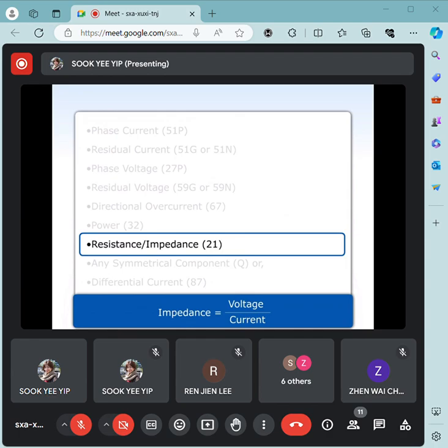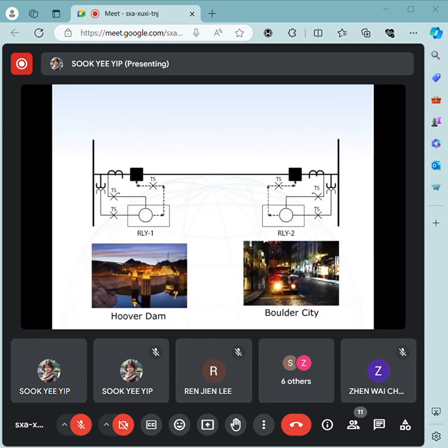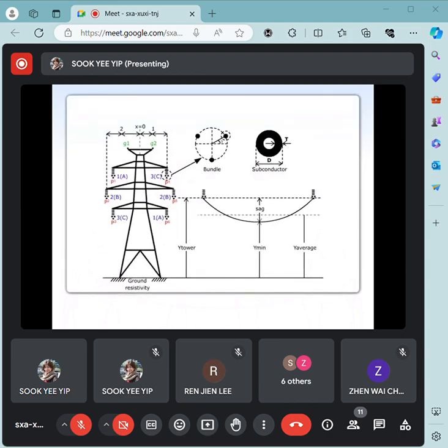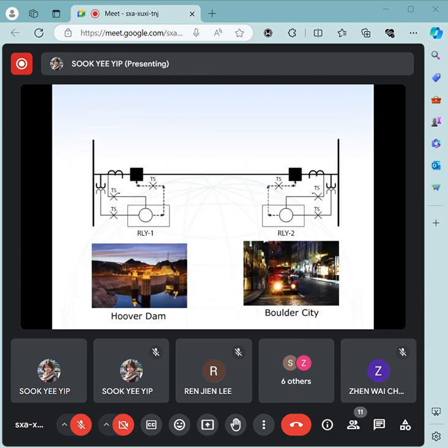In order for this solution to work, you need to know the impedance of the transmission line. You could measure it with fancy equipment, but it's usually easier to calculate it using the size of the wire, length of the transmission line, and spacing between wires. Let's imagine that we've run through the calculations, and miraculously, the spacing and type of wire works out to 1 ohm per mile.